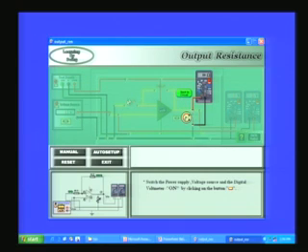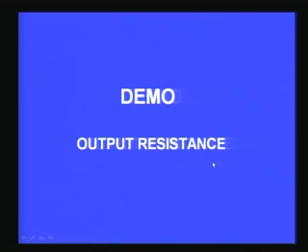You can see all the other things have been removed from the screen, only the potentiometer is there, and the 2 terminals of the potentiometer are connected to the voltmeter, which is now measuring ohms, and you see a reading of 80 ohms. So, that gives us the output resistance of the operational amplifier. So, having shown the simulation, now I would like to show you an actual measurement done on the laboratory table.